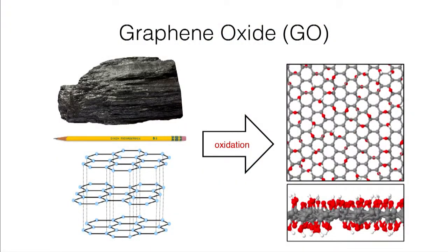And in order to do that, we're looking at carbon-based materials, graphene as a material, but graphene's actually a very expensive material to produce. And so we're looking at a much more scalable feedstock, namely graphene oxide, which is derived from graphite, which is dirt cheap to mine from the earth. Chemical exfoliation oxidizes the graphene sheets, pulls them apart into these nano sheets, which is known as graphene oxide, which looks a lot like graphene on the right-hand side, but actually is decorated with oxygen functional groups. Now, the electronics industry loves this material because it's cheap, and hates this material because it's not as good of a conductor as graphene.